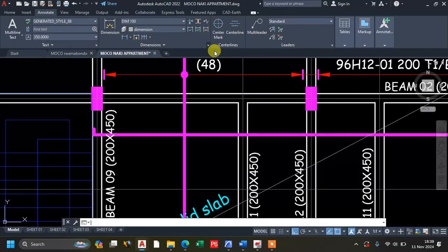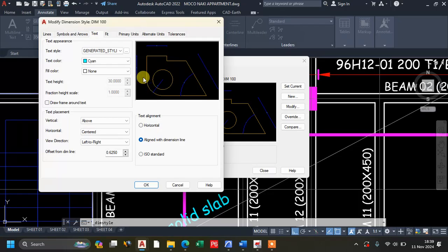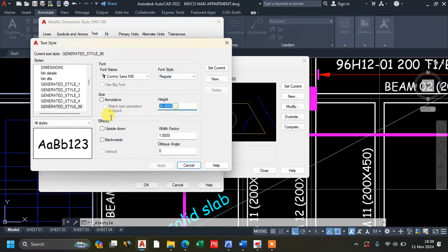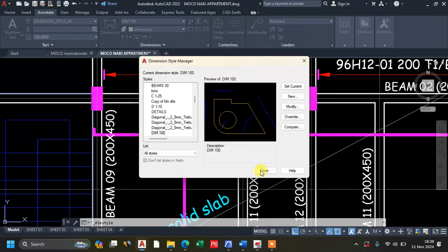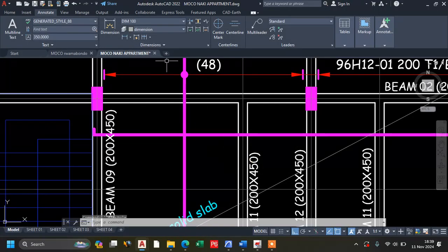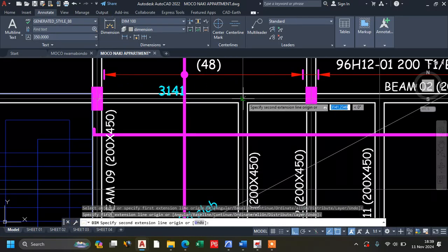I wanted to show you that the span is almost the same. When you divide the length by the width and it is less than 2, then that is a two-way spanning slab. This is my biggest span.